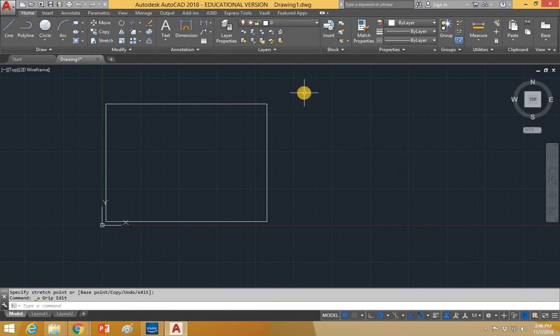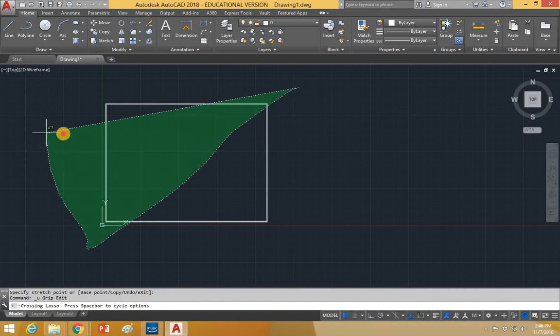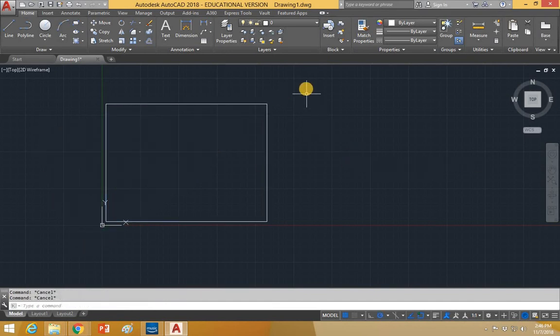What I want to be able to do is offset, and be able to manipulate just certain lines in it. So I'm going to select, and the way I can do that is if I click, and then I click again and draw a box around it. And something about selecting too. If I select from right to left, I gotta break this apart first. Sorry. Click here, click there, click explode, which is right above offset. Click explode. It'll turn my object now into individual line segments, so they're not all together.